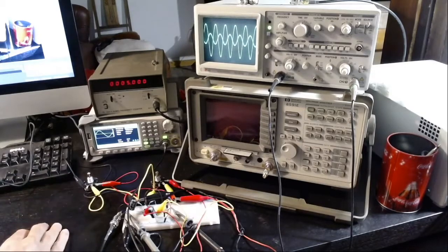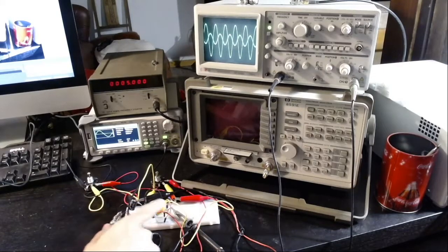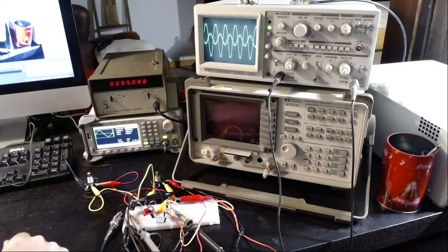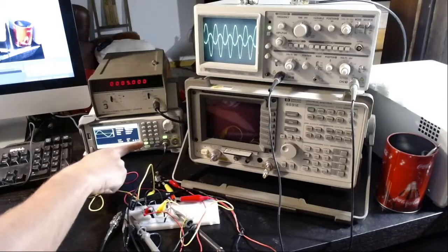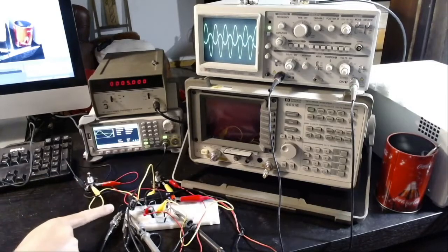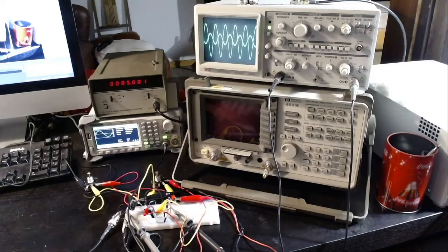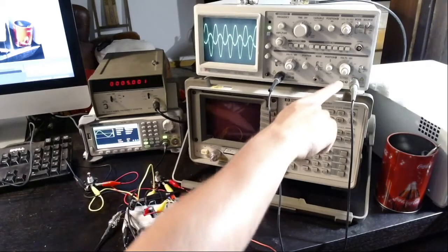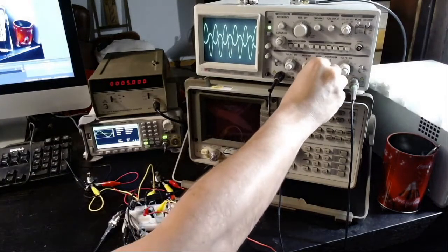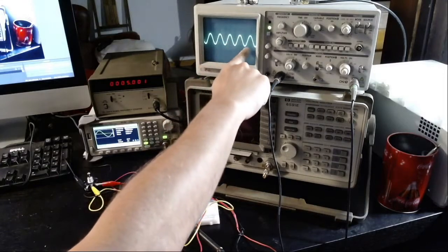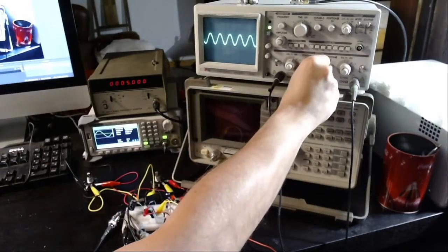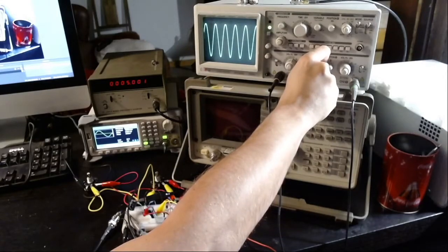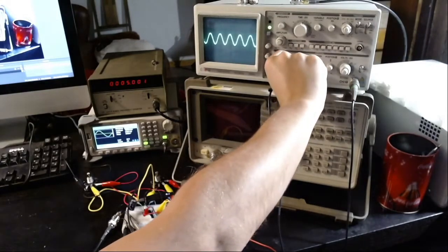So before moving to the description of the software, let me discuss a little bit about the amplifier and basically the specification. So what this is supposed to achieve. At the moment the amplifier is connected to this signal generator coming here. The input of the amplifier, coming from the signal generator, is going to channel 2 of the oscilloscope. So this is this signal here, currently at 100 millivolt, and the output is this larger signal, which is indeed amplified.